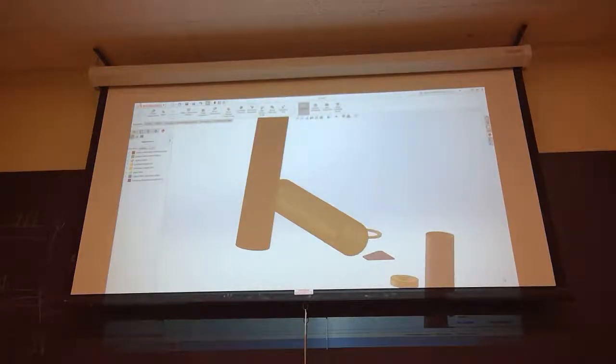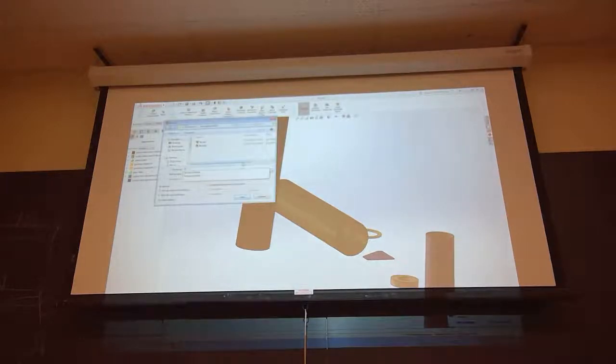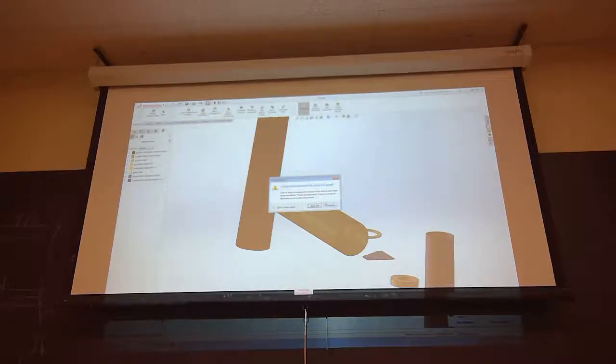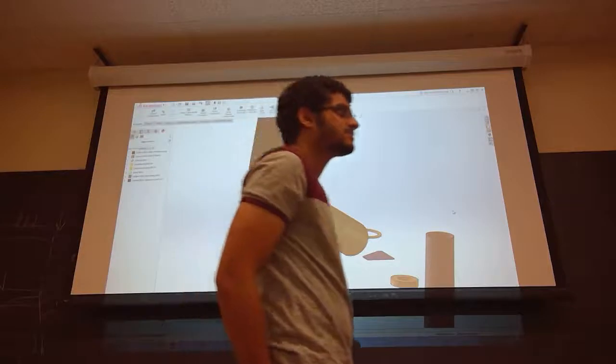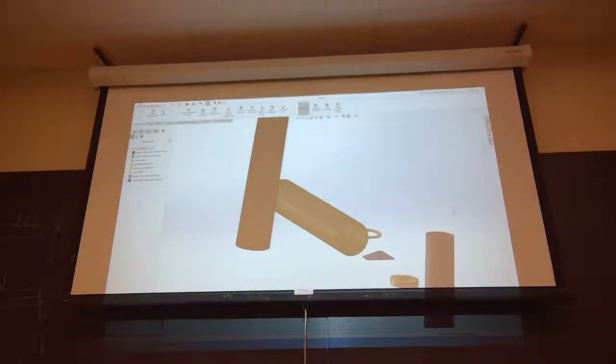Make sure you save your document. You can name it Rocket something else. If you save it as Rocket, it's going to overwrite. Does that mean if I want to rebuild before saving? Yes. It just makes sure that all the components are at their newest state. So if you're editing components while you're in assembly and you don't rebuild, it's going to use the old ones.